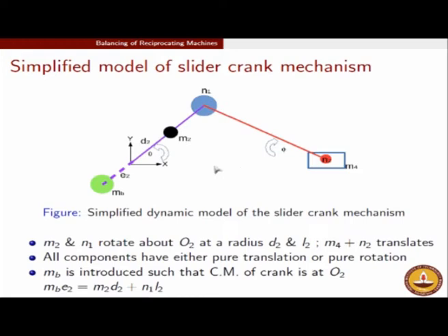So at this stage with this counter mass, what have we achieved? We have achieved our objective that there are no rotary unbalances left in the problem. The crank was having rotating unbalance, the connecting rod which was simplified to two lumped masses, one was having rotational motion and the other was having reciprocating motion. The fact that one was having rotational motion at the crank pin was very useful in deciding a mitigation procedure, as I was referring to a few moments back.